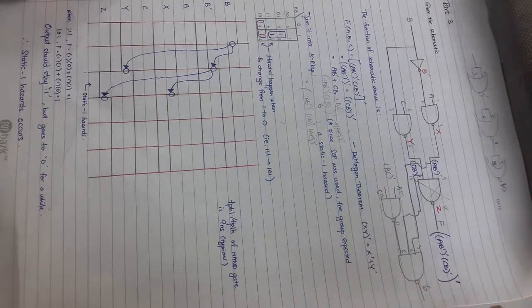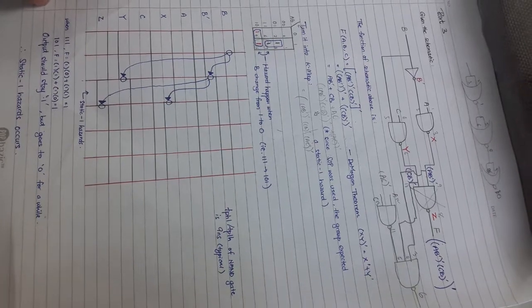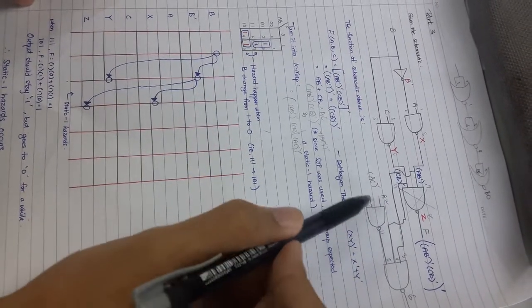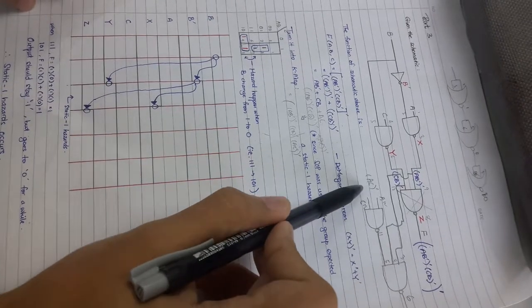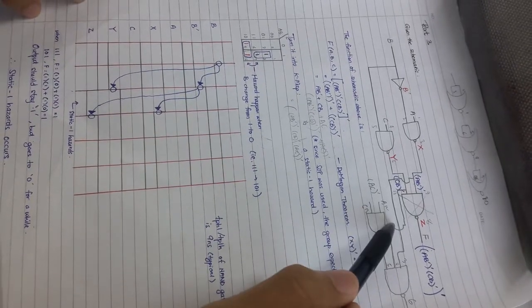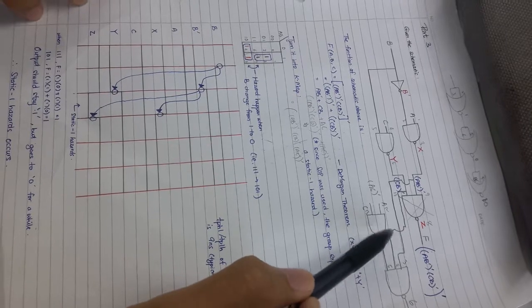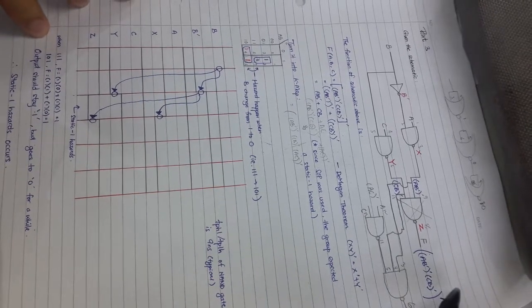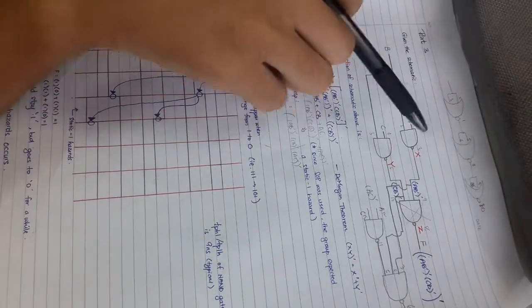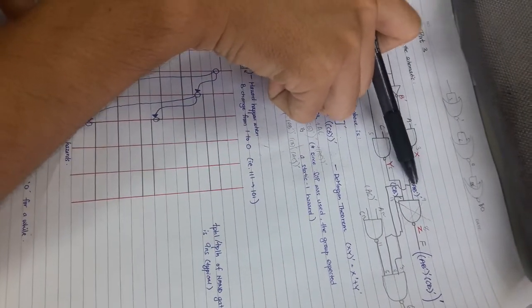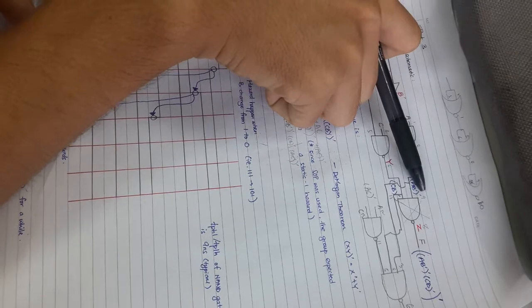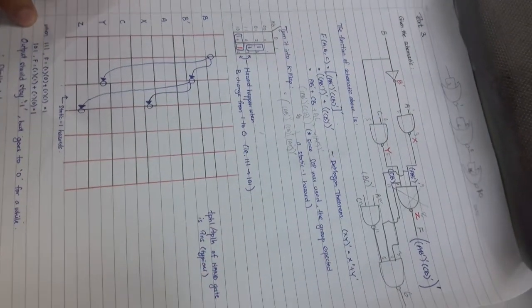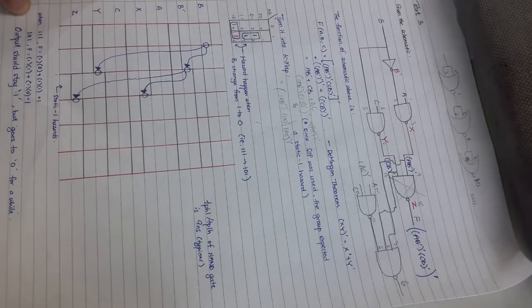So to remove the hazard, we add in one more NAND gate, and the input is A and C, and we connect this one to a 3-input NAND gate, and the other 2 inputs, which are from the previous ones, which are A, B not and C, B not, to resolve the hazard.